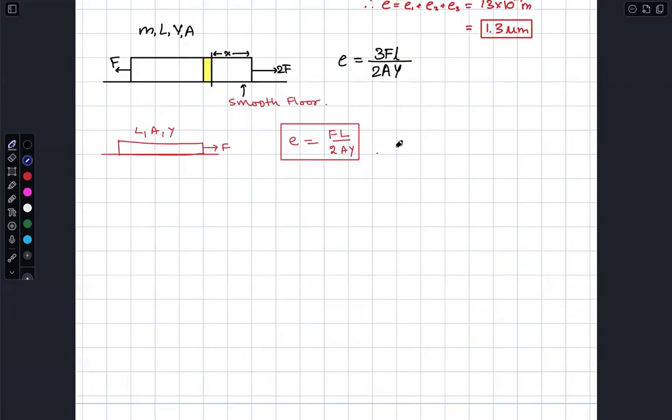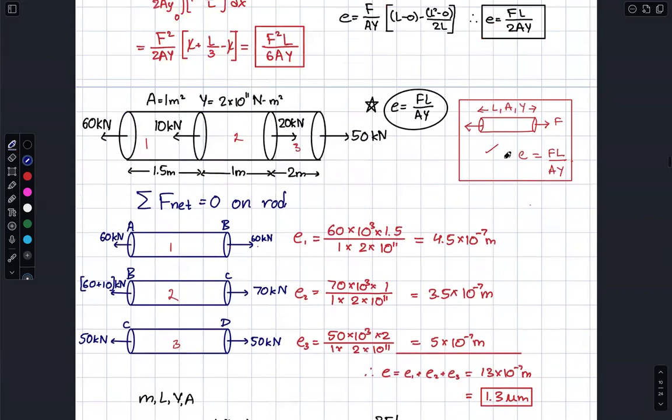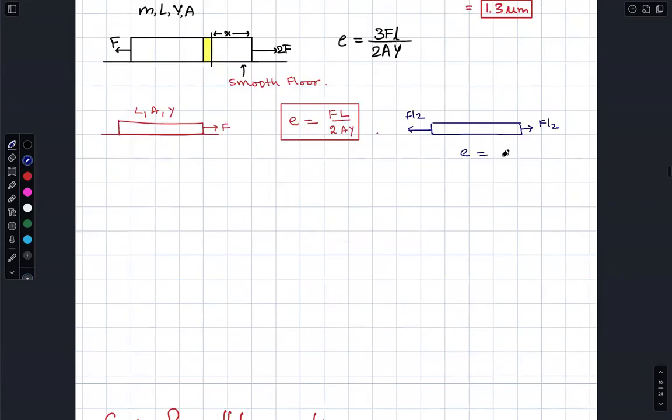So, in this case, what I have done is, I treat this problem the same as a problem like this, in the reference frame of the rod, I can see that F by 2, F by 2. In this case, Aryan, please try to remember, the elongation is F into L by AY. Same concept we got.